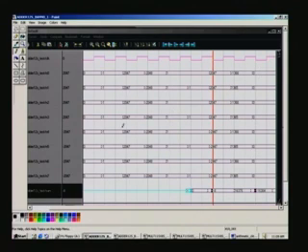And so, I will zoom this here, and let us say we have already seen that there are 5 pipeline stages inside. So, naturally the result must manifest only after 5 clock cycles. Let us have a look whether it is so. The result starts here, you can see 0 here, this result. After zooming you will be seeing it clearly. Right now just be content with the waveform that you get here. So, 1 pulse here, 2, 3, 4, 5.